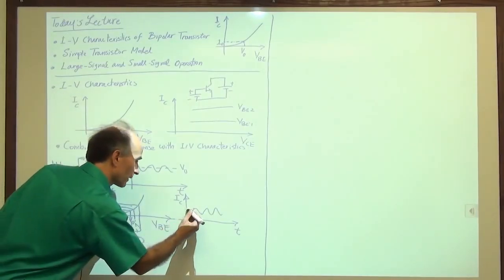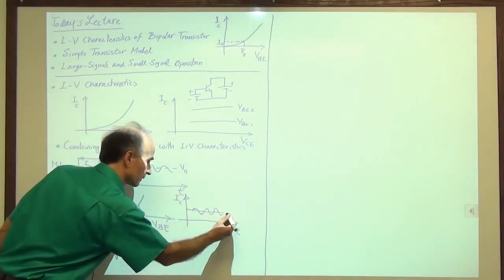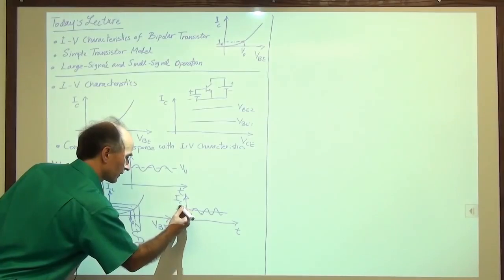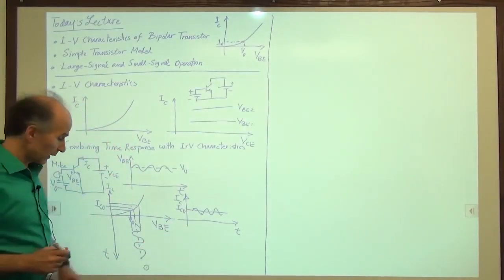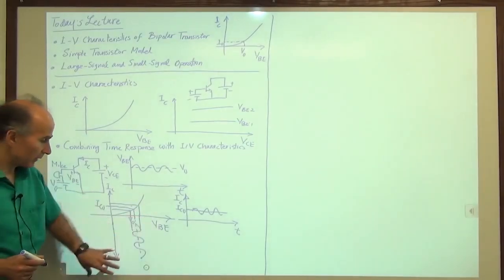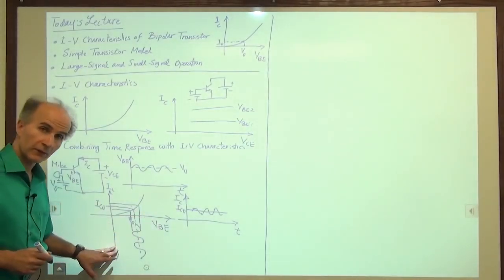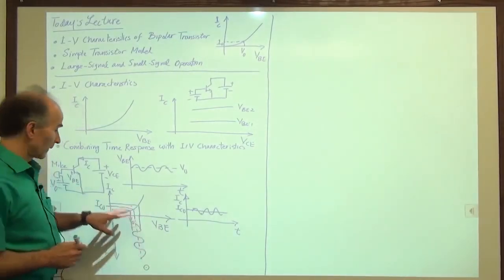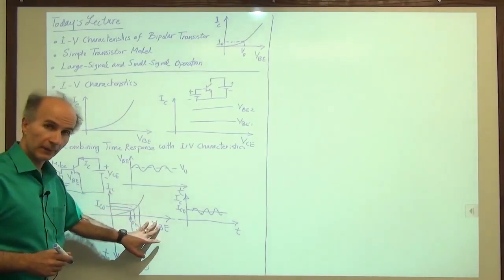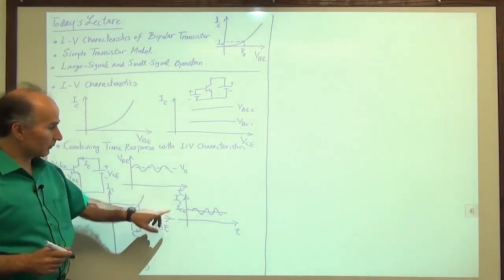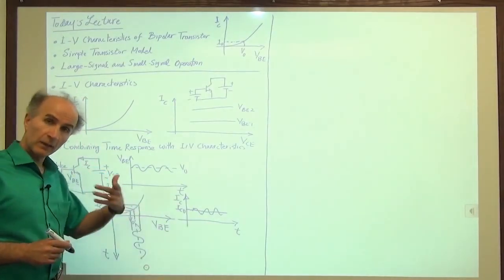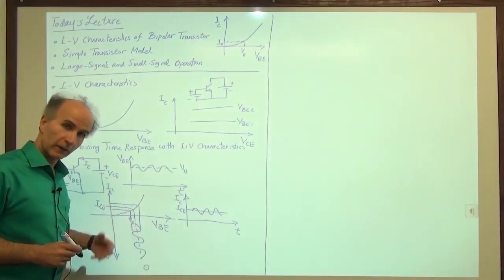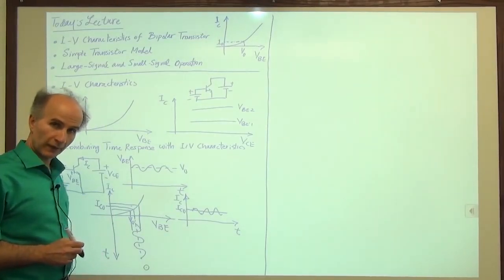Okay, so the bias value is in the middle of this approximately, and its value is equal to IC0. So combining the base emitter versus time plane with the IC versus VBE plane allowed us to plot IC as a function of time. It's pretty simple, but very intuitive and very clear in what you should expect.